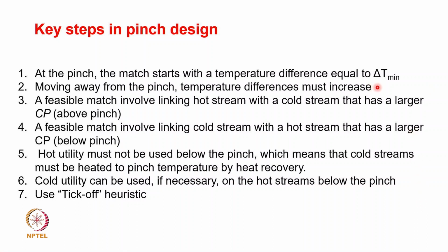So 2-3 points are to be looked into in the pinch design, and they are the following. At the pinch, the match starts when the temperature difference is equal to delta T min, and moving away from the pinch, the temperature difference must increase. So we will see these 2 points.